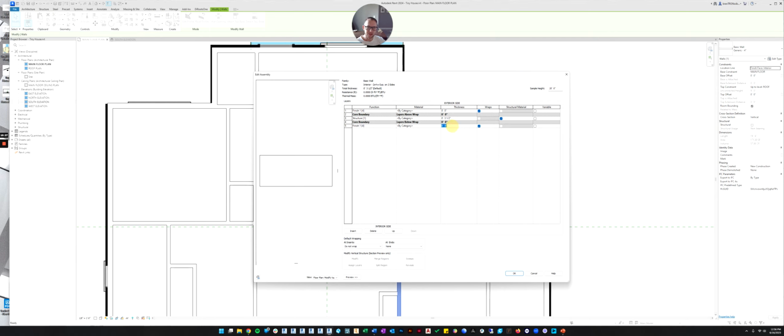All right, we're also going to give it a dimension. Sheetrock comes in a couple different dimensions. I'm just going to use 1/2 inch. So we're going to put 1/2 inch here and 1/2 inch here. And you see when we add a dimension how our wall changes? So now you can see the gypsum board, the 2x4 layer, and then the other gyp board layer.